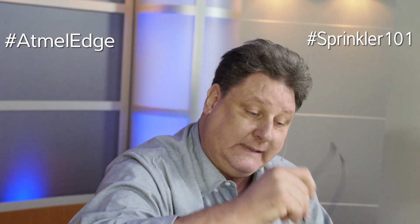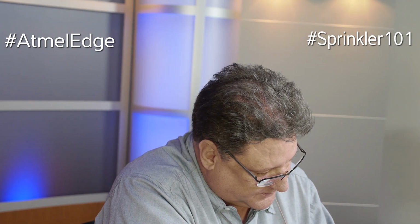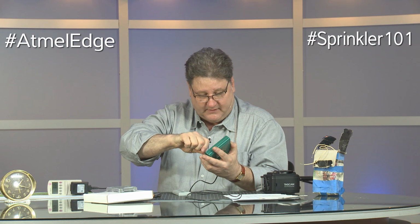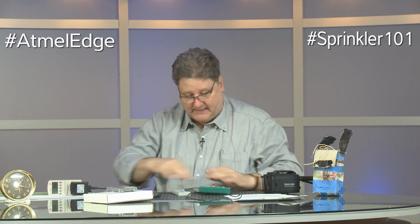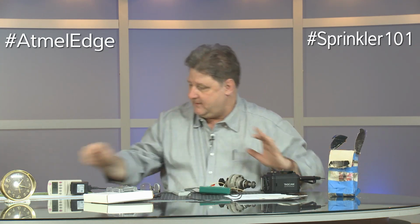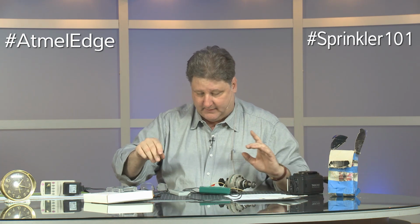This is going to be a little sketchy because we're doing it live, but the people do it to my products, I'm going to do it to theirs. So we're going to hook up the 24 volt AC. Sprinkler clocks run on AC. If you run them on DC, the wires and the valves and all the stuff in the ground corrodes terribly. So this is an AC transformer, AC going in here to run sprinkler valves. Here's a sprinkler valve. So let's look at our 2 watts. So quiescent power, 2 watts. That's just nothing plugged in, nothing running.